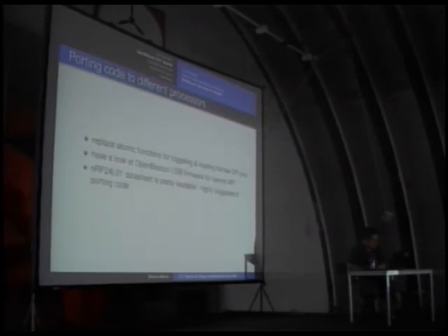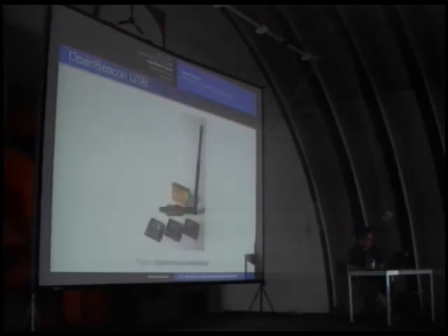And if you have a bigger processor, then have a look at the OpenBeacon USB firmware, because there you have a layered API. And definitely, if you want to work with either OpenBeacon USB or the CCC Sputnik, you have to read the nRF datasheet, which, if you compare it to other datasheets, is pretty verbose.